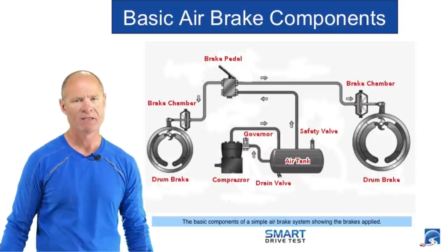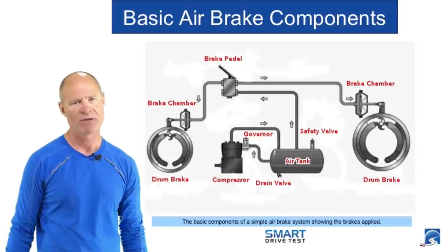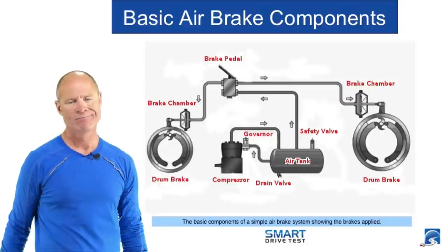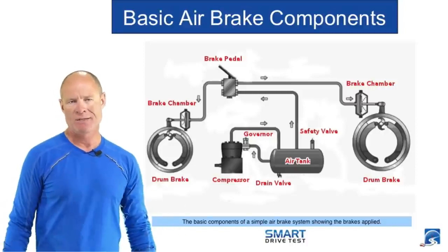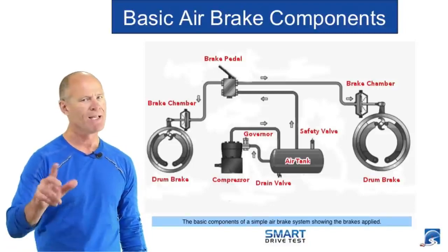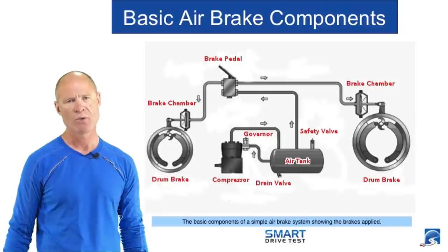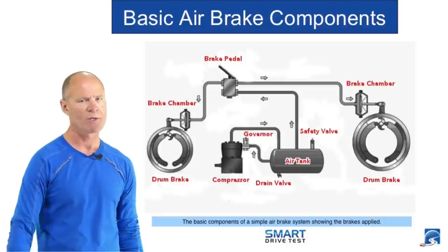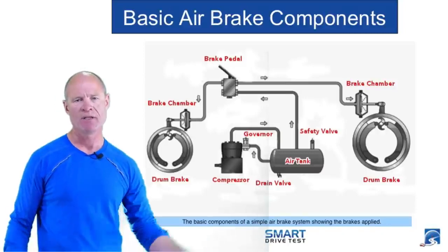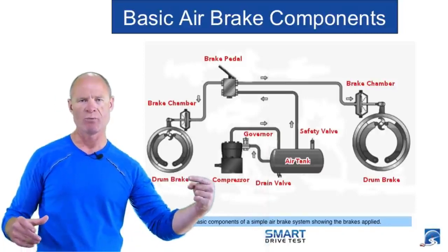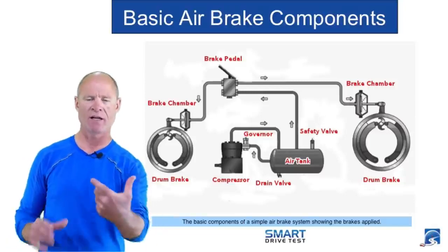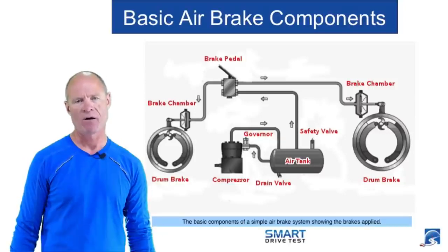Wedge brakes, in the 20 years that I've been teaching air brakes, I've only ever seen wedge brakes once, and that was on a trailer on the island, and it was kind of a novelty to take the students out and show them wedge brakes. The question on the test for wedge brakes is they may have 1 or 2 brake chambers. That's the question on the test. As well, to identify a wedge brake, the brake chamber and the push rod will be facing into the brake assembly as opposed to at a 90-degree angle as they are on drum brakes.